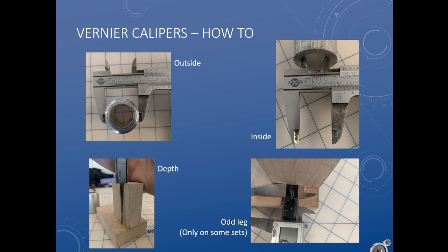So I can use these as an outside caliper. These jaws here are my outside measurement. The jaws are sharpened. See, we've got this sharp edge here, this sharp edge here. So a little bit of a slant is less of a problem. If I'm a little bit cocked, I'll get a better reading on the sharp faces. So there we go, 0.14865 inches. Let's flip that, see it in fractional inches, see it in millimeters. Isn't that convenient?